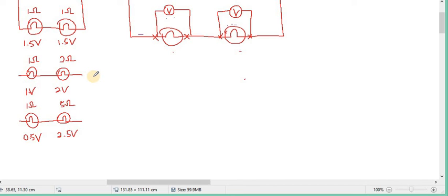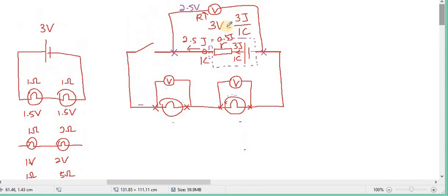Okay, now remember this concept where if the resistance is higher, then it will get more of the energy. This is a very important concept. So we go back to here. So you can understand why the voltmeter will get the vast majority of the 3 joule. That means out of the 3 joule that the charge carries, 2.9999999 joule will go to the voltmeter. So the internal resistance maybe only gets 0.00001. So if you look at the reading of the voltmeter, it will show 3 volt.